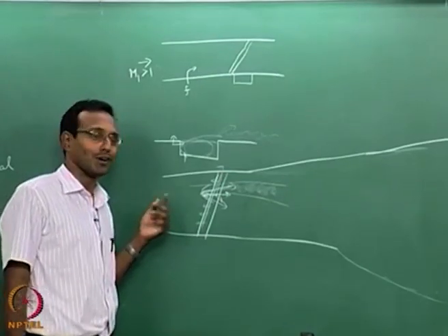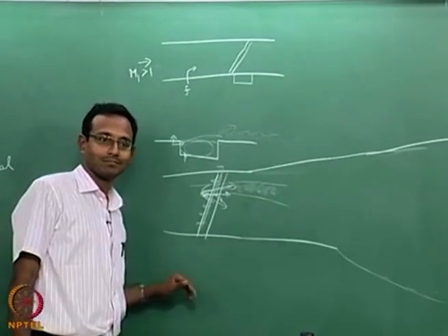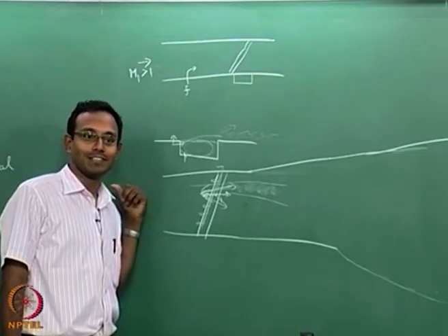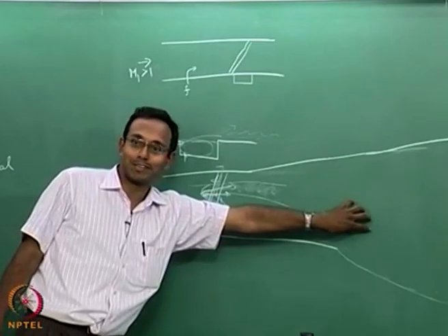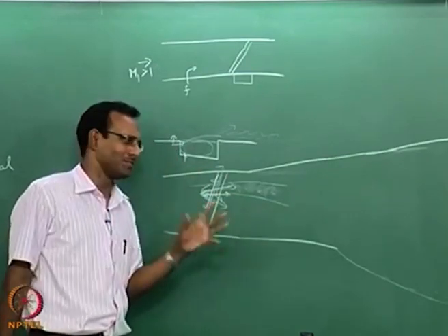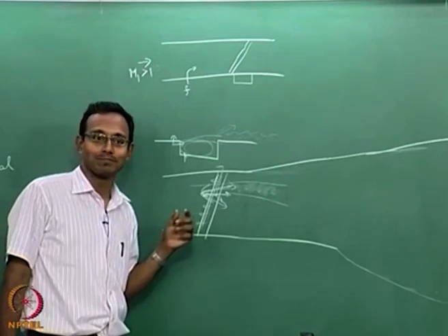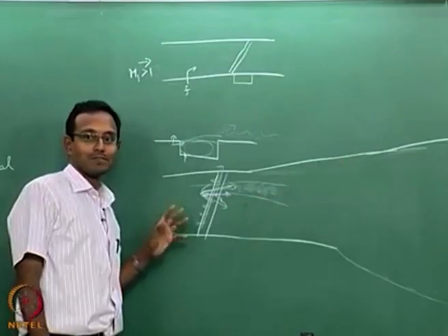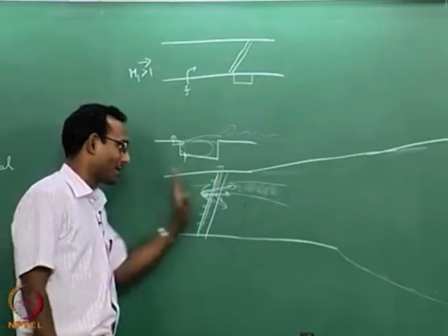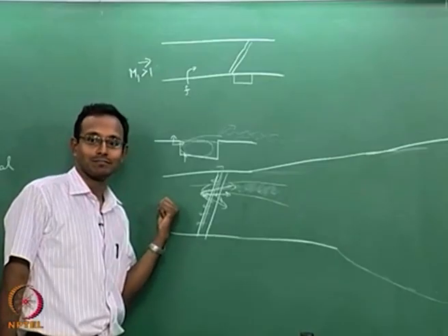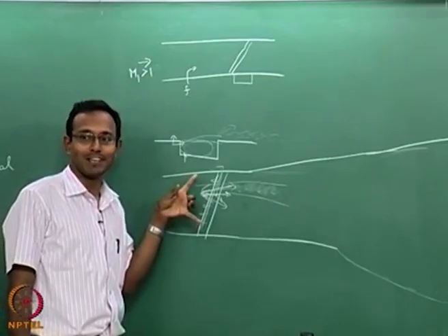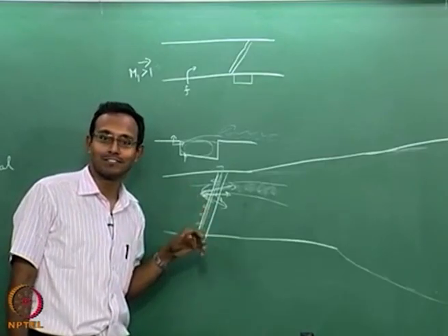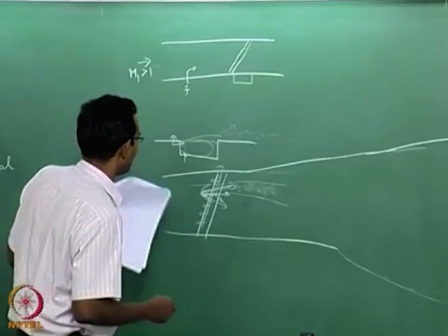And then now I have to think about how to pull the shock back in. How do you pull the shock back in? I have to increase P naught of the flow somehow. Increase the P naught of the flow or decrease my back pressure really low, so that the shock goes downstream. Think about our nozzle problem, where we keep on decreasing the back pressure, the shock goes more and more downstream. Something like that you have to think about. Then that shock will be going past this, and I can go back to starting condition. It is very difficult when I am flying using this engine and the engine is unstarting. I cannot accelerate very well and go to that condition. That is where things go wrong. This is one case.